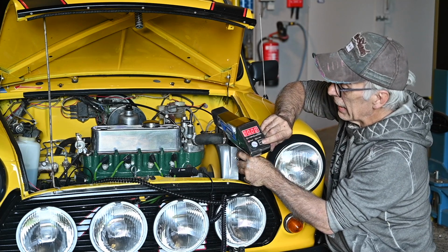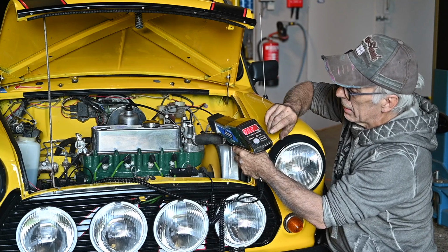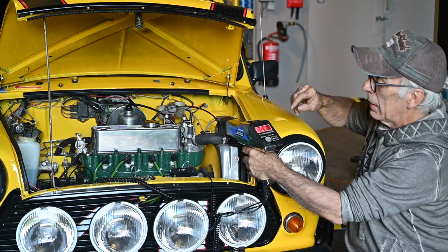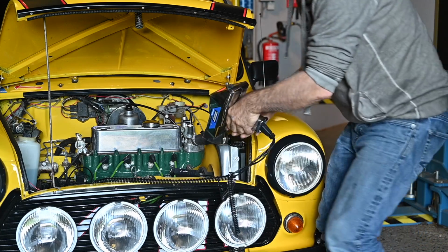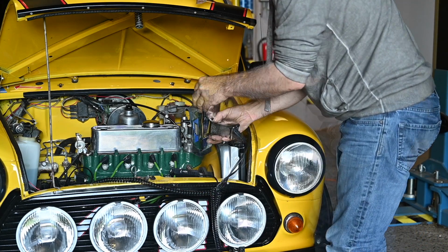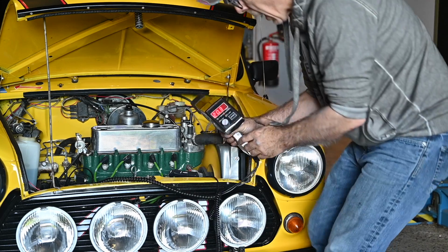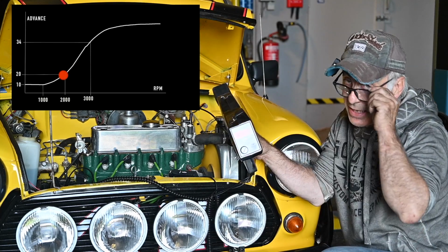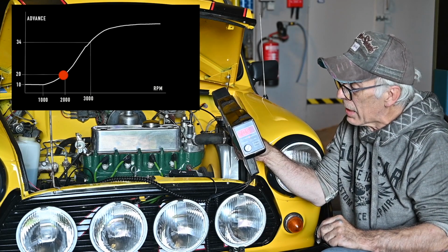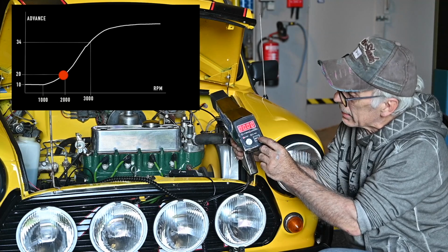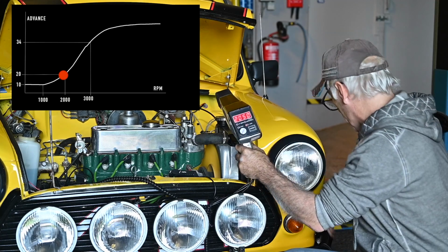And for that one, I need to select the advance, right? So there we go. So right now it's set to 0. I don't know what it will be. So let me check this and adjust it. And I have about 20 degrees advance at this rate. So now I'm going to increase the RPMs to the next level and see how much we're going to get. So let's check the RPMs and crank it up a bit more.